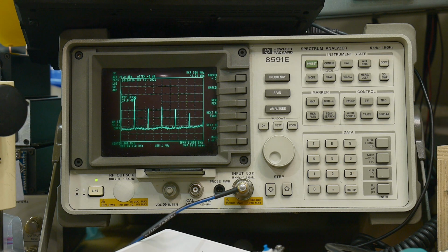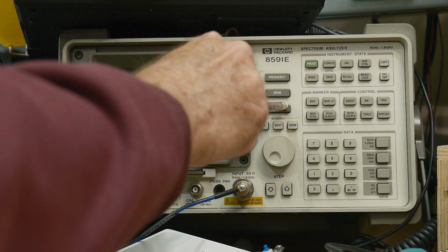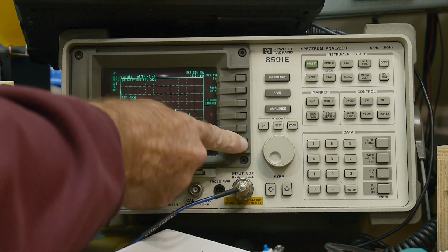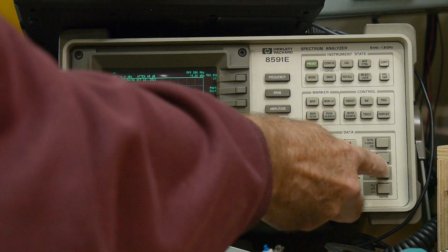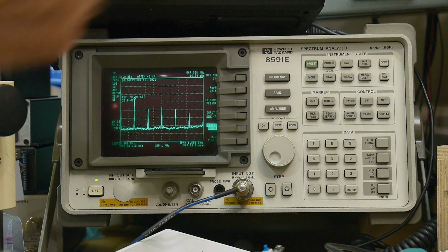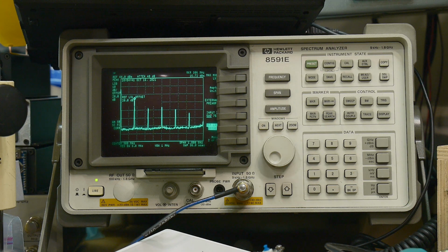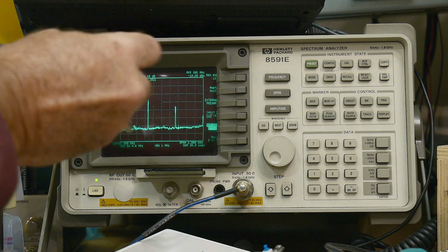All right. Now we've put a 20 dB pad in there, so we're not measuring correct, okay? But I can say amplitude, reference level offset, 20, and now we're measuring correct. Now we're measuring plus 16. Okay, so it's just a mathematical trick. All right, so let's try some other frequencies out here. This is at 300. Let's set it to 600 megahertz. And yeah, so it's just the same.